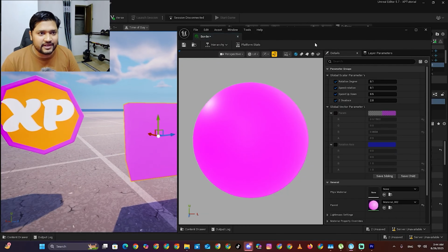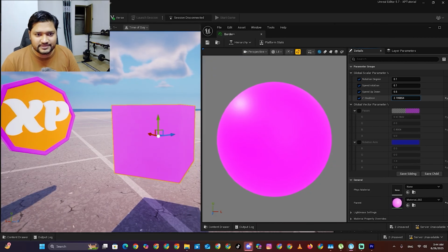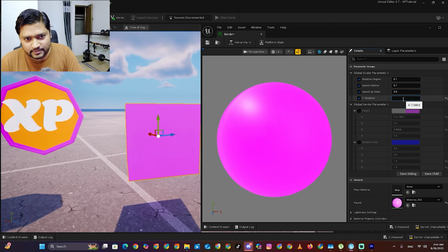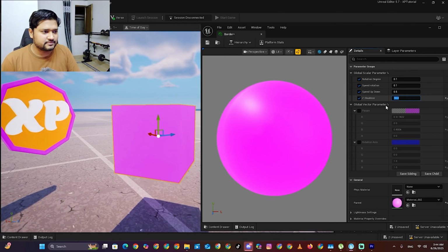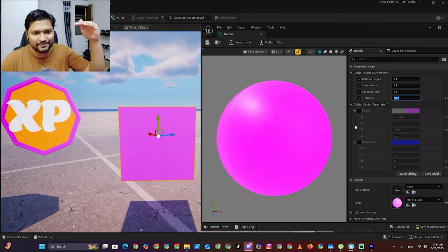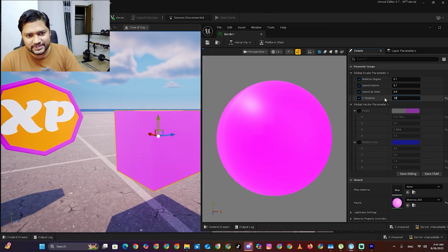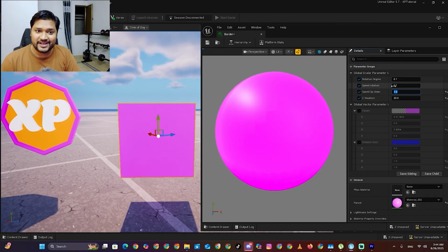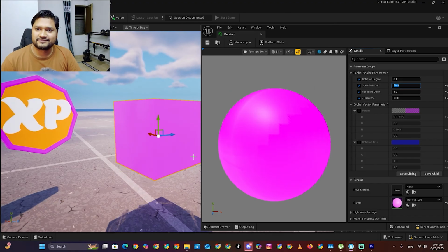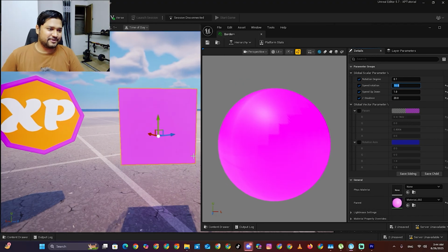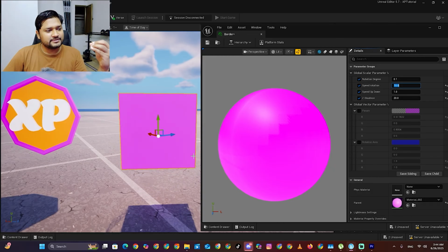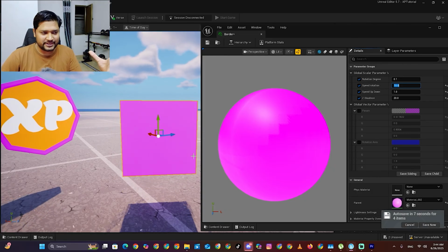And if I double click on it, let's change some of the parameters like Z distance, maybe 10. Yeah, let's do some fun. Sorry, my one on numpad is not smooth. Yeah, it is moving more up and down. So you can apply this material on any object and change the parameters. Now it is moving more up and down, speed, let's make it 1, and it is moving faster, and rotation speed should be 10. How it is moving like this. So this was the reason why we converted that constants into parameter. So you can create the material instance and use it on any object and move it with just materials, without using words, without using any constant.